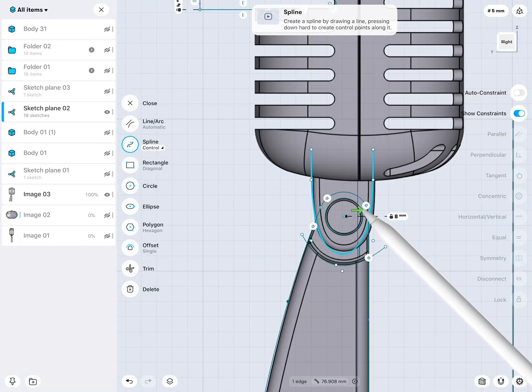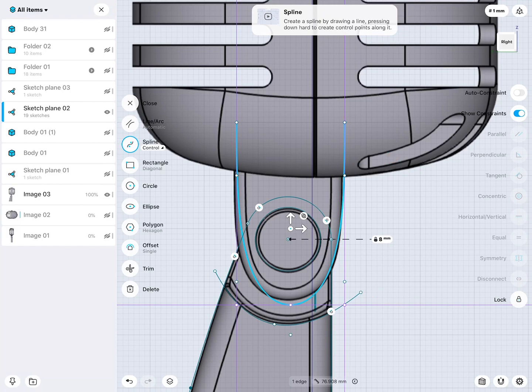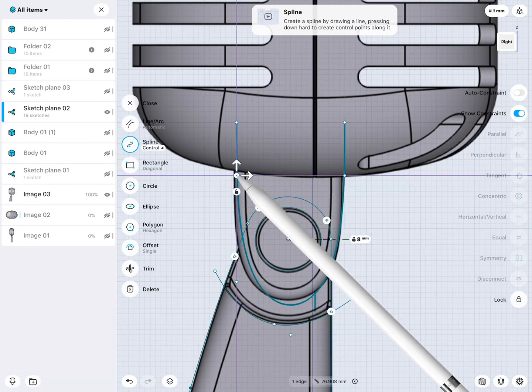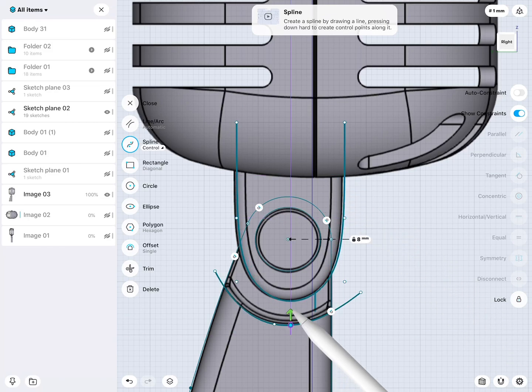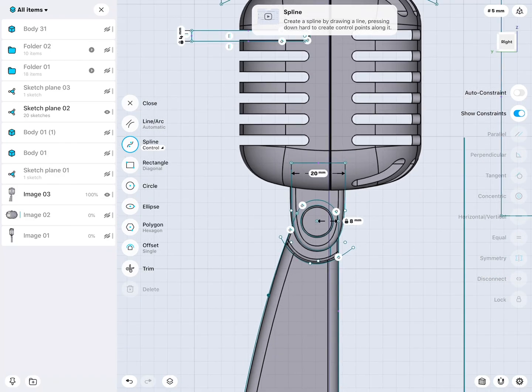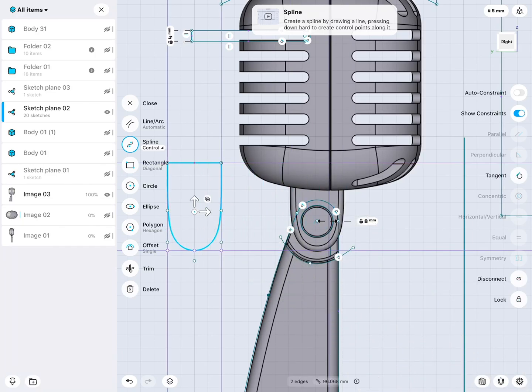Bring this over. Now this is now better. These 2 dots here, or CVs, I can bring down more. Bring this one up again. Now be careful that you don't lock elements together. I need to close the sketch here too. Very good. Double tap on it and just move it out of my way.